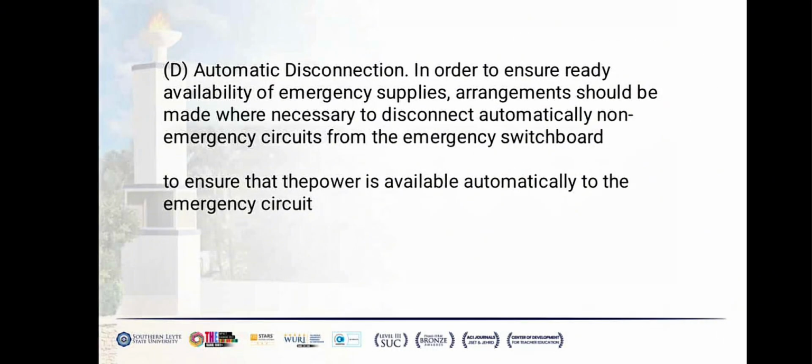Automatic disconnection. In order to ensure ready availability of emergency supplies, arrangements should be made where necessary to disconnect automatically non-emergency circuits from the emergency switchboard to ensure that power is available automatically to the emergency circuit.